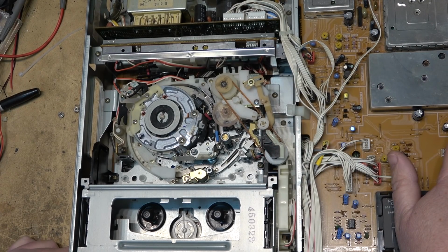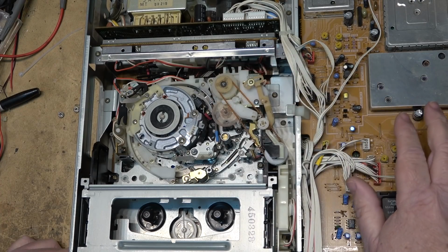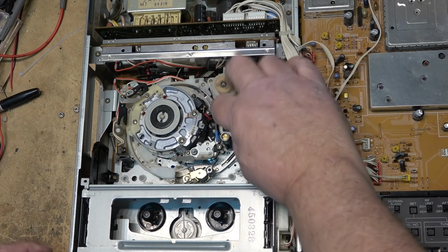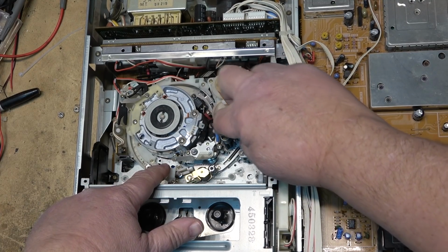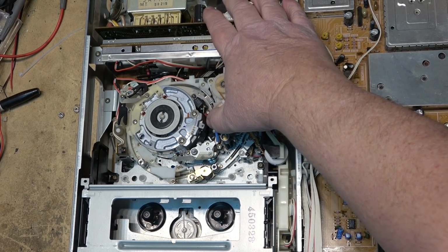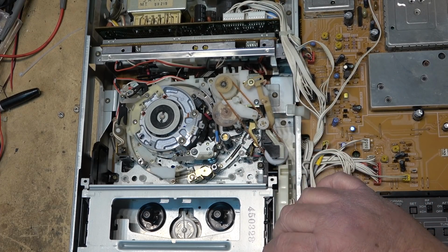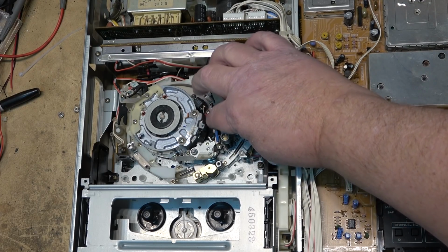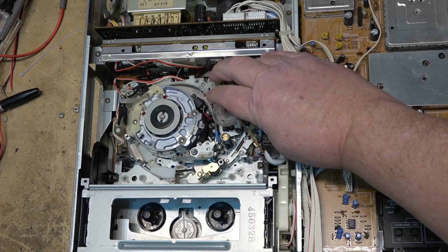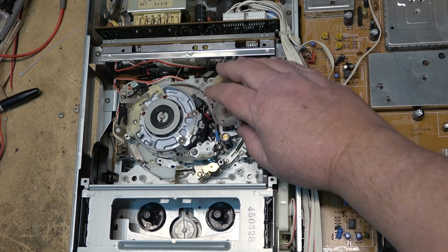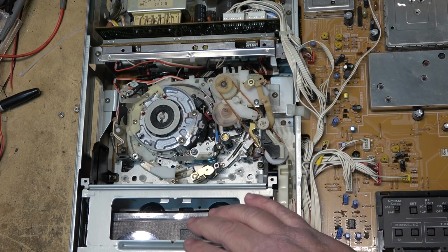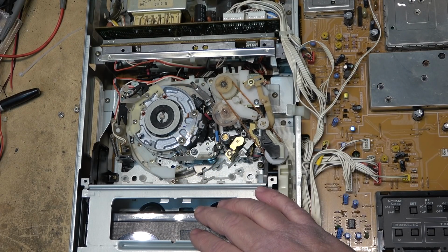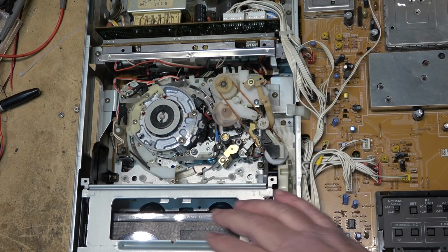What that solenoid does is that operates the power split device. So this one motor, when it's turning one way, or when it's in one position, it will operate the loading gear, as you can see down here. If I turn it on, it should kick the tape back. Actually, it should unload. With my luck, it's broken. It should reset itself here. There it goes.